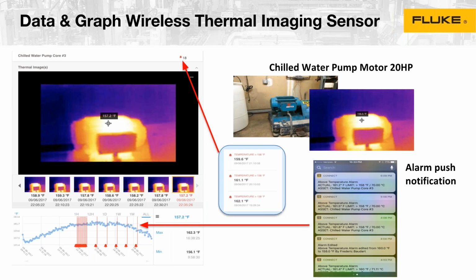And I think one of the key aspects really when you talk about wireless, anytime you do any kind of measurement remotely, and I think that's important, this is not just for the thermal aspect, but any kind of remote measurement, is having the ability to have alarm push notifications. Because this is why we do this remotely. One of the aspects is that if I can have an alarm, I could be going on my way to work, or I could have multiple people on my team, and we all get a push notification that somehow this particular motor has finally reached 180 degrees, and we need to do something about it. So we can make the decision right there, right then, and have a quick call on the way to work, on the way back from work, and say, okay, we need to act now, and not wait until we come back the next day, figure it out, then do vibration or other measurement. Later on, there truly is an issue, and then we have a failure on this piece of equipment.